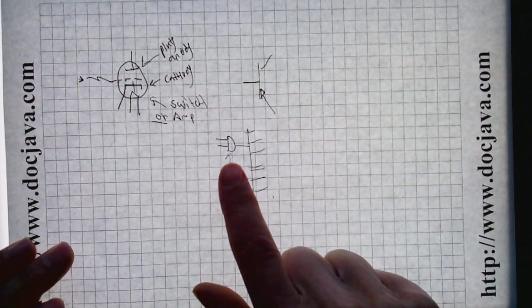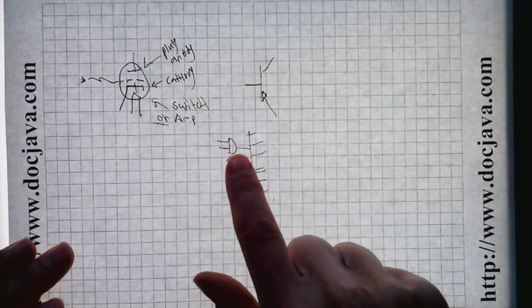They will not do what's expected because you put too much parasitic capacitance on the output. They don't drive infinite load from these AND gates, so you've got to limit yourself to the same family of gates and typically 10 inputs. And even 10, sometimes it depends on how long the wires are, because you get so much parasitic capacitance per foot when you have longer cables.